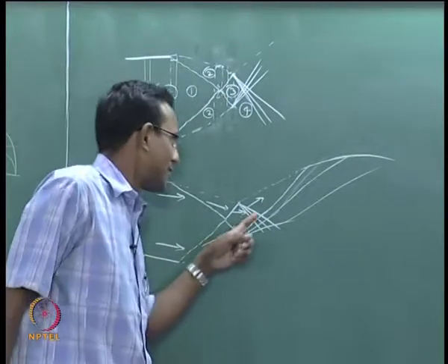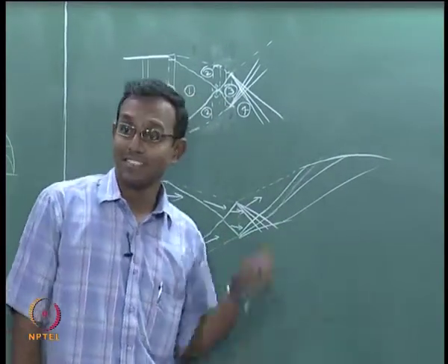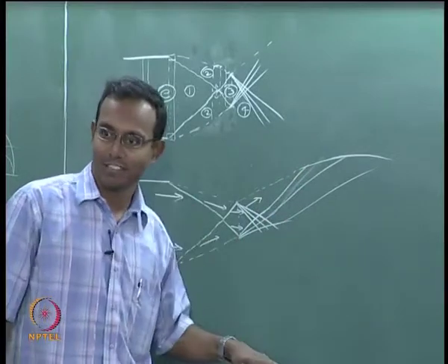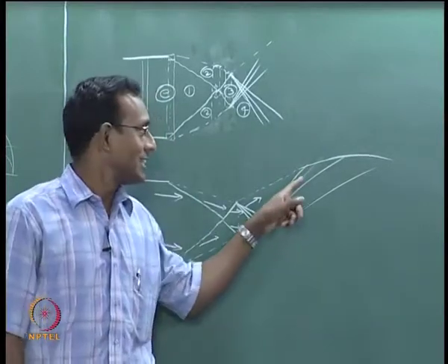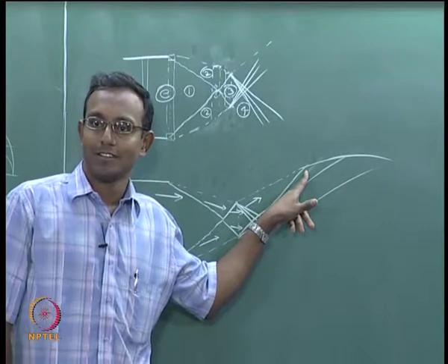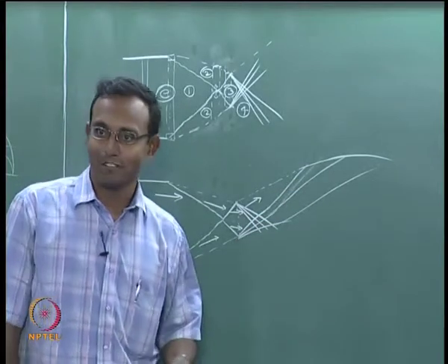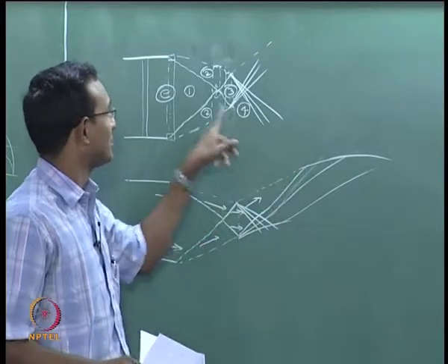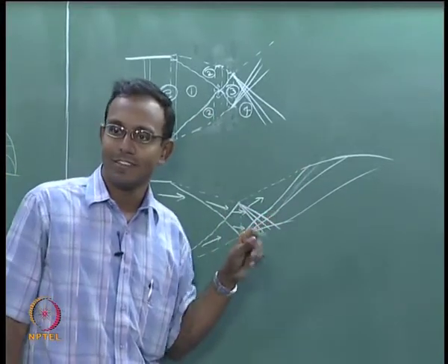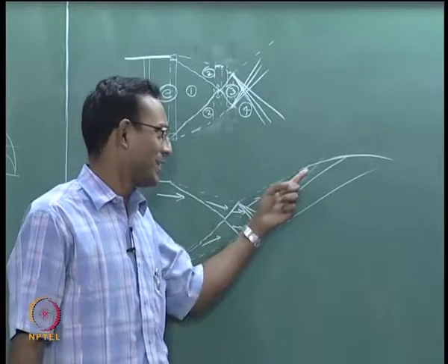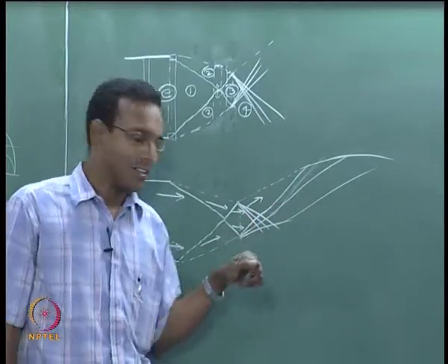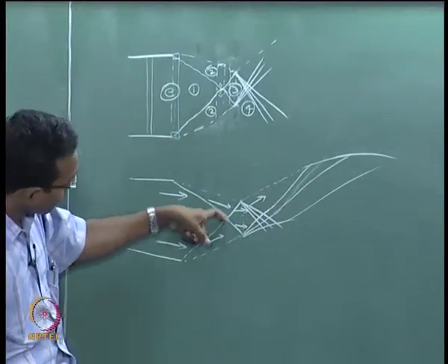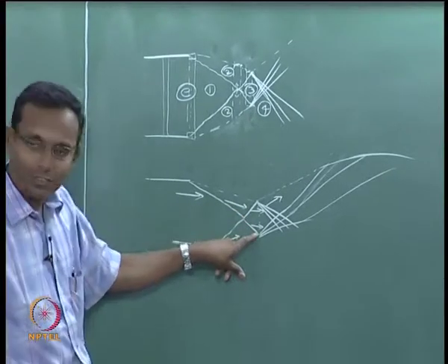What happens when an expansion wave hits a boundary, which is again adamant? It is going to say the pressure has to be fixed. Expansion tells it to decrease pressure, so it will be replaced by a compression wave which will tell it to increase pressure. Why is it a compression wave, versus previously it was a shock? It is just one expansion wave going, so it needs to be replaced with one compression wave, while here there was a whole bunch of compression waves together coming as a shock.